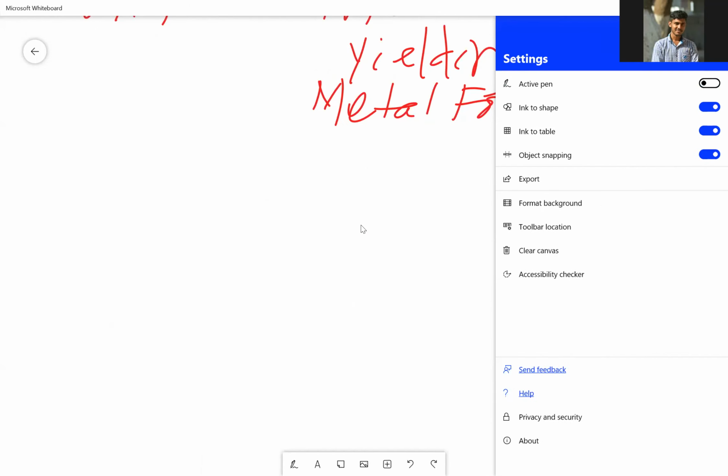The principal shear stresses for a cube whose faces are principal planes: for each pair of principal stresses, there are two planes of principal shear stress, which bisect the directions of the principal stresses. Remember this.